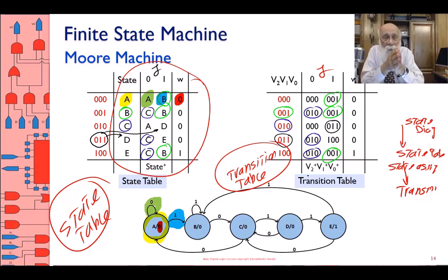But the Karnaugh map can only tell me the output of a combinational circuit. This has timing in it. This transition table has a flip-flop in it, implying some kind of flip-flop here. I don't want that. Karnaugh maps can only work for combinational circuits, not for sequential circuits, and therefore transition tables have to be turned into something different. So I look at the transition table and say, okay, let's turn it into a combinational circuit.